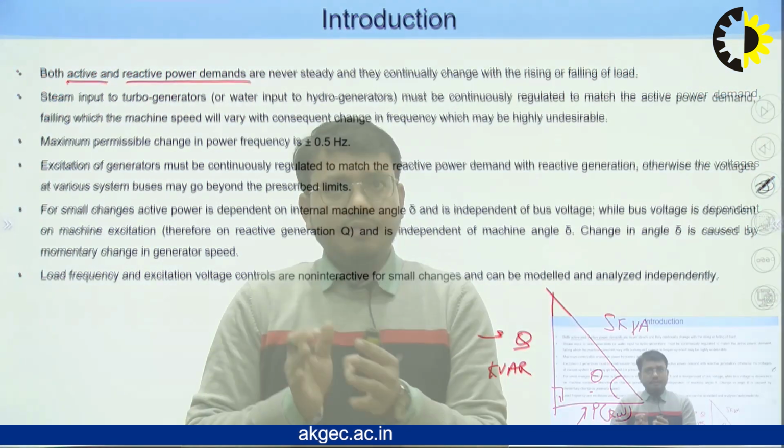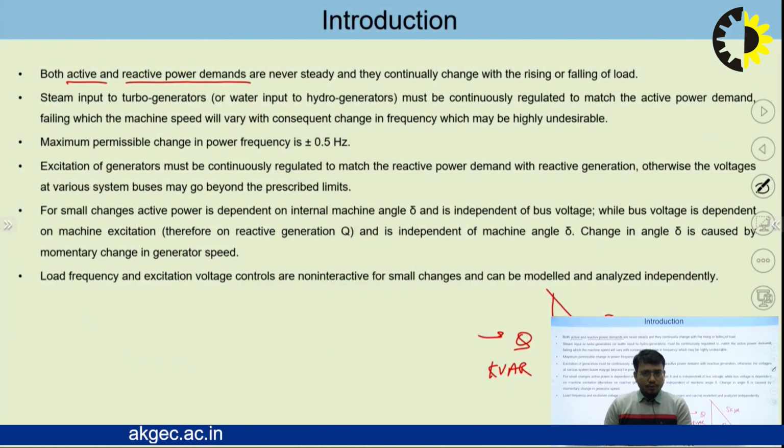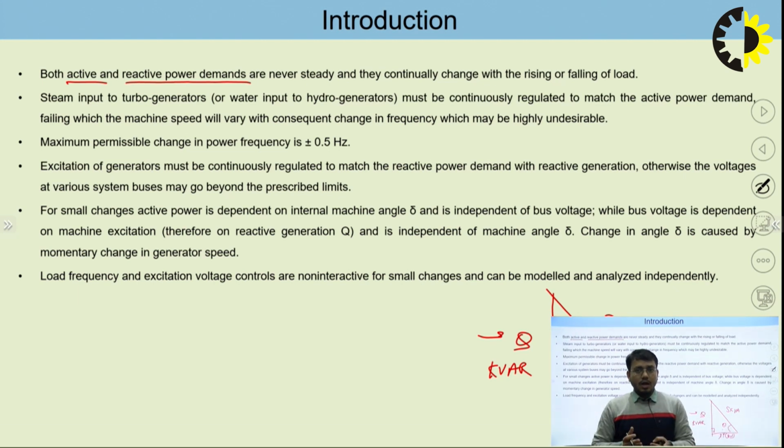So if you have, let us say, 500 megawatts of load, you must have at least 500 megawatts of generation, and along with the load we have losses and reserve capacity as well. Depending upon the power required at the load, the transmission losses and the reserve capacity, the amount of power that has to be generated at the power plant is increased.